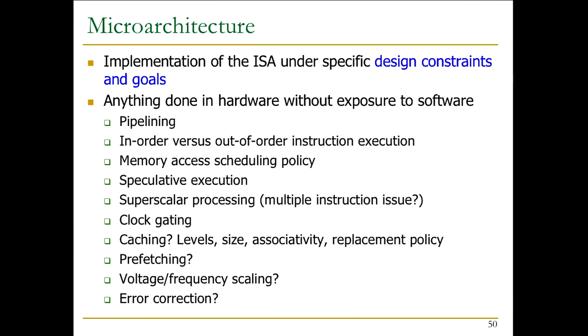And this mentality, what you would potentially call crazy thinking, generated a lot of research into compilers at IBM, and that's actually the reason he got the Turing Award, because he had this crazy idea that you should expose the hardware at the very low level to the compiler, and make compilers that optimize programs by taking advantage of these very low-level control signals. At that point, the control signal is part of the ISA, right? That sounds terrible. In the end, that's not what's happening today, but that gives you an example, right? Any of these can be part of the ISA, but most of them are not today.